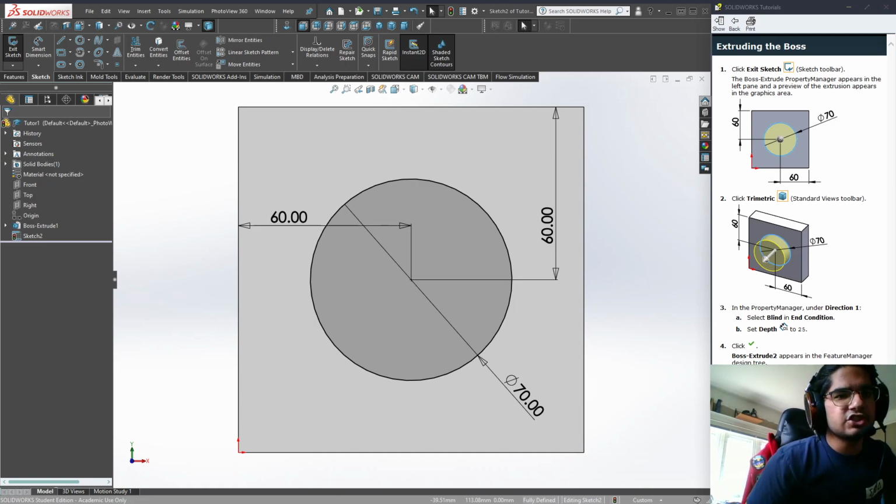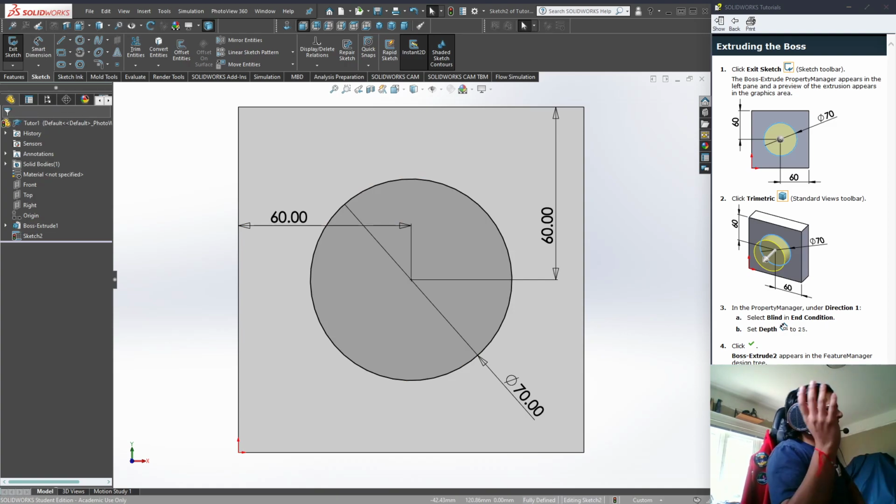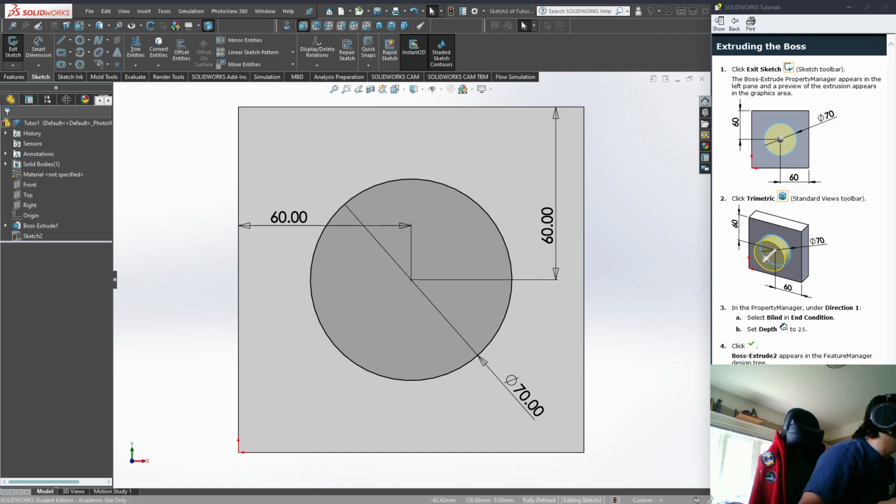It's called feature browser, the part browser, whatever you want to call it. I forget what SolidWorks does. Feature manager design tree. Okay. So we're looking at the feature manager design tree here. And if you look on the left, you have a bunch of sketches, planes, and your initial boss extrude. So if you see that sketch 3, you're just going to double click on that.